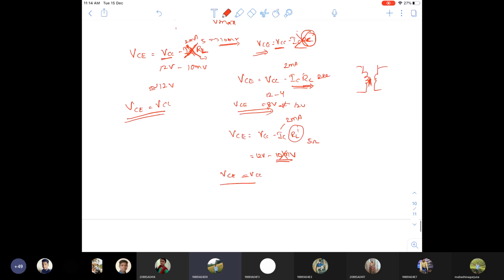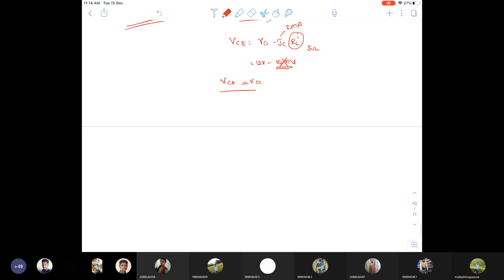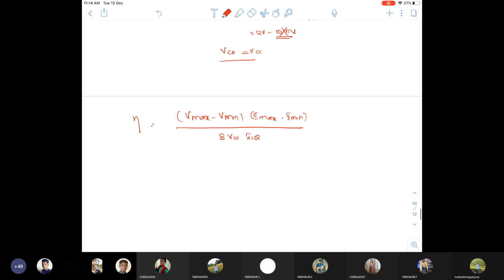Yes, sir. So now efficiency is equal to, again I will write the formula, (Vmax minus Vmin) into (Imax minus Imin) divided by 8 VCC ICQ.